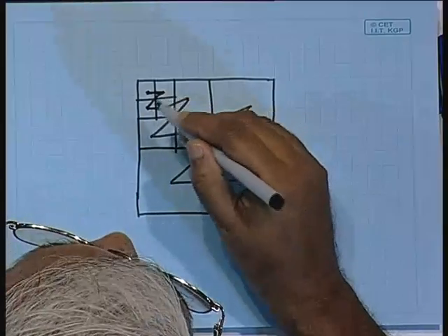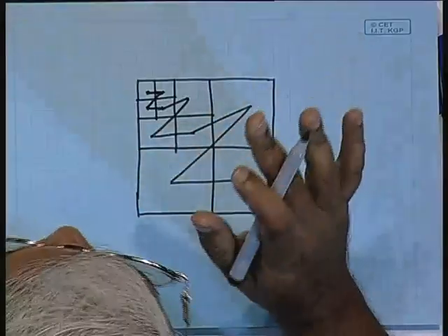Now, there is a great trick, okay, which has been suggested by Shapiro, and that goes like this: since you are traversing in a tree like this, you form a tree first, and then whenever you are traversing the tree in this order, if you find that a particular coefficient at a higher level of subbands is insignificant, let us say 0, and if you find that all its descendants in the tree are also 0, in that case there is no point in encoding each and every 0 coefficient.